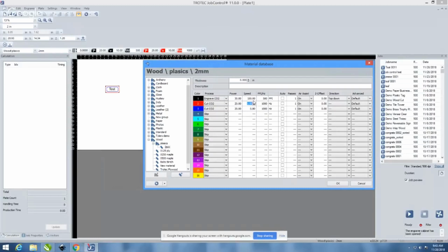Yeah, so just make sure, guys, that you're engraving. It does happen to me almost weekly. You're trying to get your settings in quick, and instead of 1, you might type in 100, and that is not going to be good for your file or your material. Or vice versa, you might type in 0.80 for your engraving, and of course that's going to be way too slow to engrave anything with any good quality. But just keep an eye on that, guys, and you should be fine.